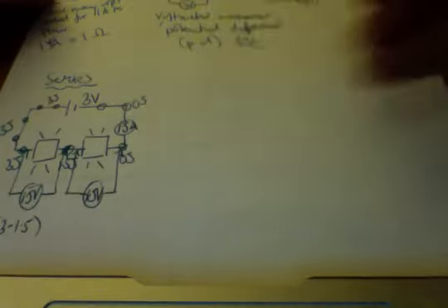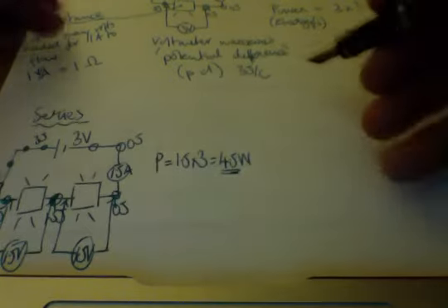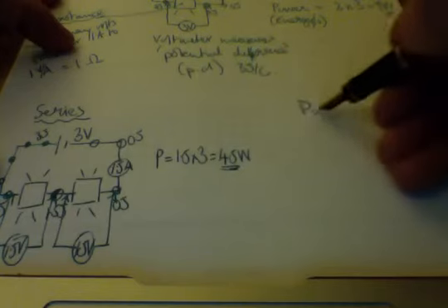Fantastic. Just to make sure we've got a complete measure of this circuit, let's look at the power output as well. Well, we have 1.5 coulombs per second coming out of the battery, and each one's carrying 3 joules, so therefore my power is going to be 1.5 times 3, which gives me 4.5 watts of energy. Excellent. Okay, now let's turn to a parallel circuit.